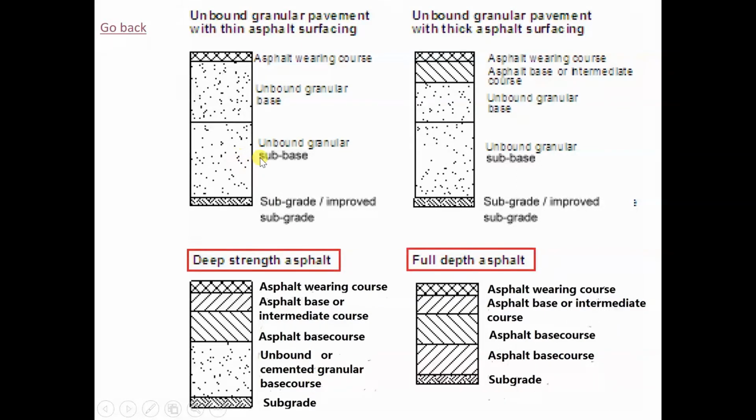The top part here we could do as the subbase, soil subbase. Anywhere above, base course and subbase are all just aggregate, and usually the subbase has a bigger aggregate size. I got this one from the Austroads.